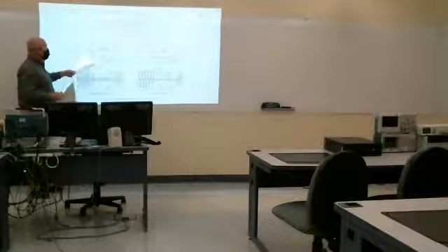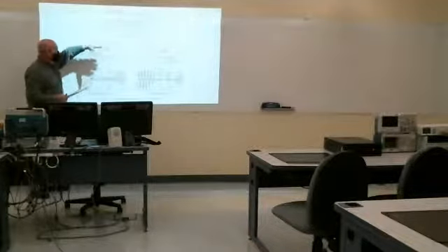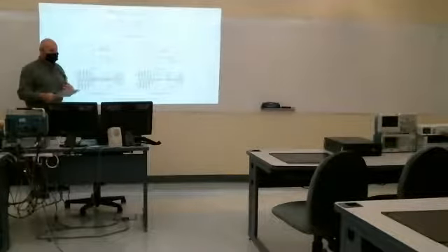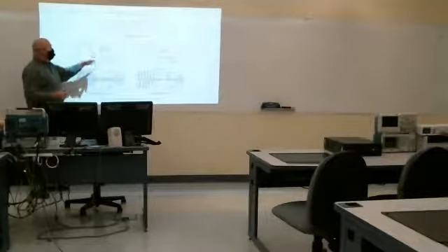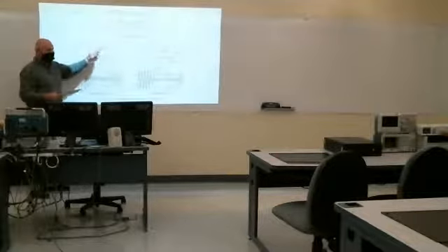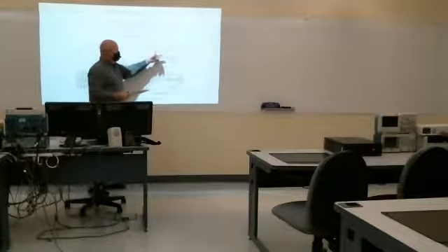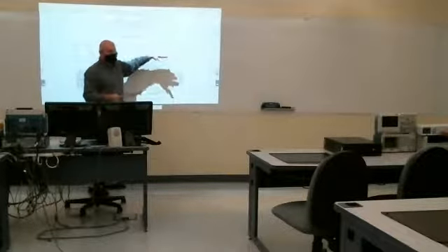A has to be large enough so that the whole waveform, A plus x(t), never goes negative. And that's being shown here when the modulation index is less than 1, that happens. Okay. When the modulation index is greater than 1, then it doesn't happen.